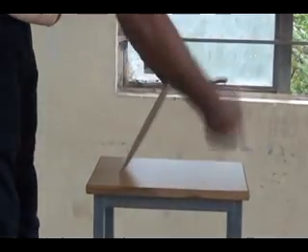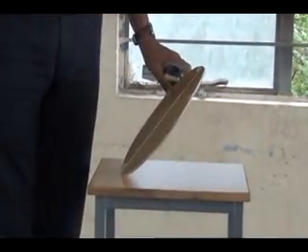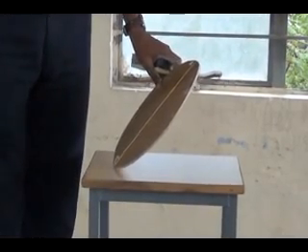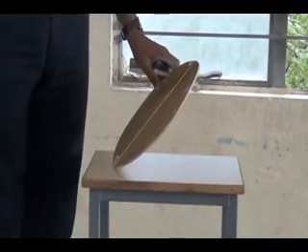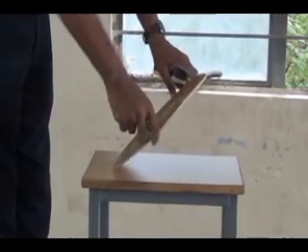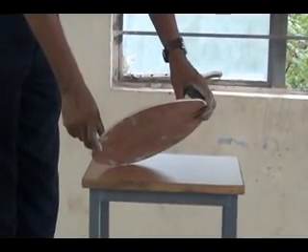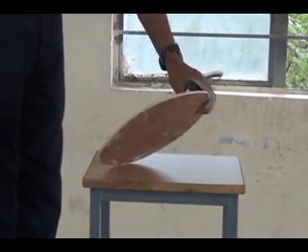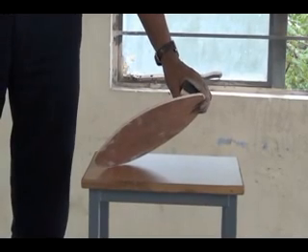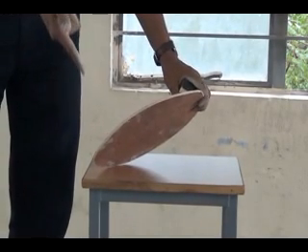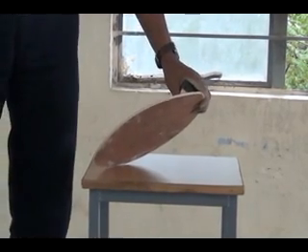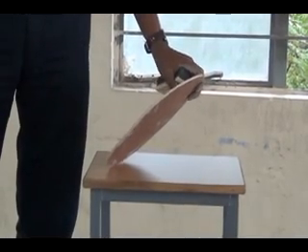So this inclination is nothing but my HP, right? And the diameter AB appears to be inclined 40 degree to VP. This diameter AB in the top view will be like this. You can see the diameter AB appears to be inclined 40 degree. Even though in this orientation the surface is 30 degree inclined to HP, the diameter AB that I have drawn is 40 degree inclined. Is it clear? So straight away you can proceed.